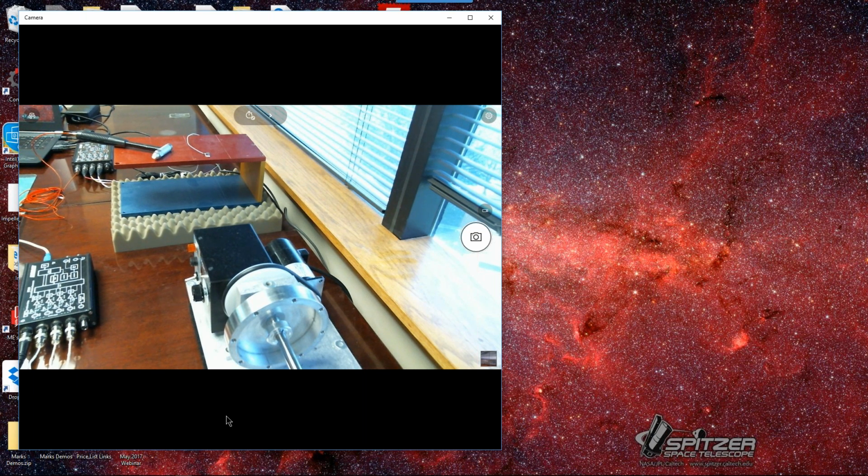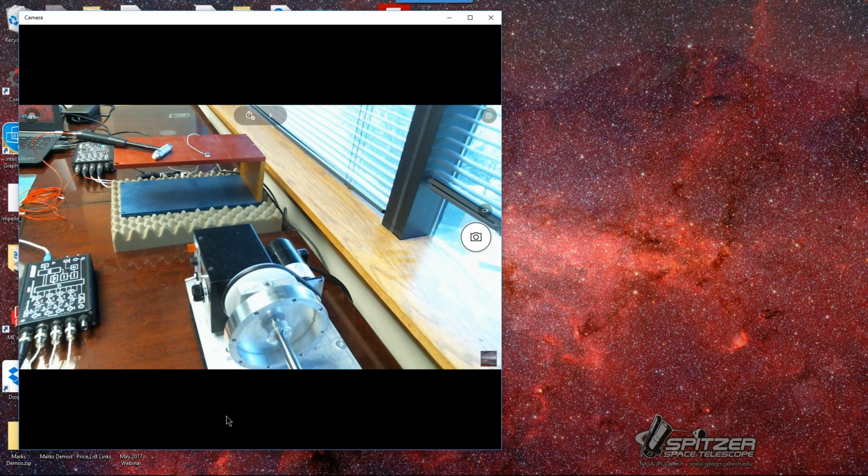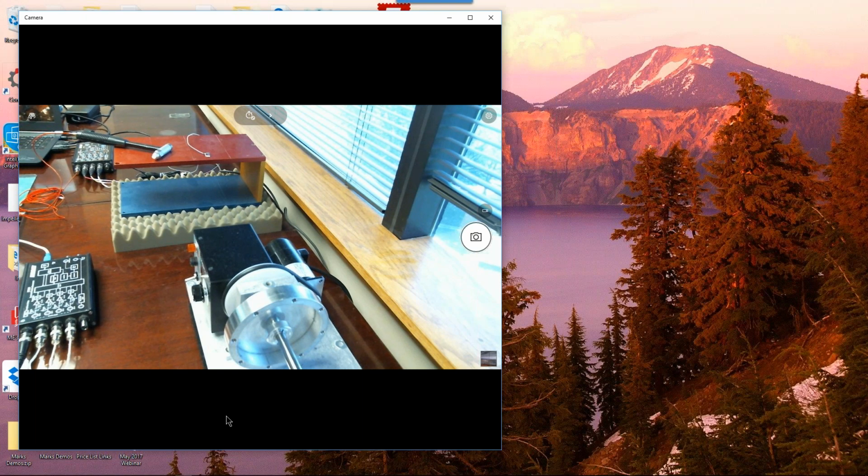And if this were a machine out in the field and I was doing troubleshooting with MEscope to look at its resonances, look at its ODS data, probably the easier way to do it would be to impact at a single point and rove an accelerometer around, especially if it's a triaxial accelerometer like this one.